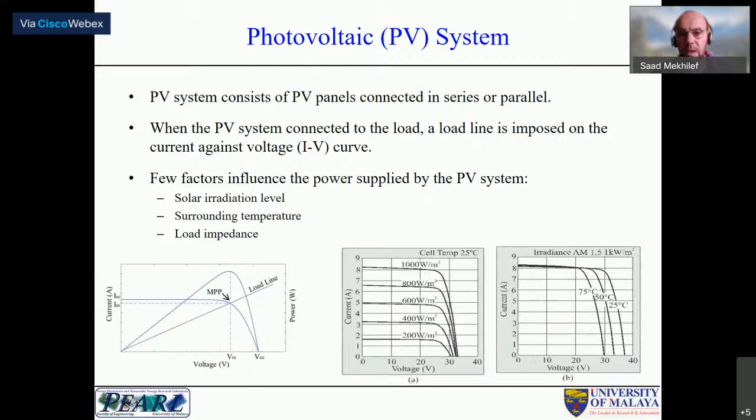This is just to review the characteristics. These are very common characteristics. We know that the PV output changes depending on the watts per square meter received. This is the current, and we call it the IV curve, at a fixed temperature, for example 25 degrees. The temperature also has an effect on the power produced by the cells. As the temperature increases, the open-circuit voltage drops, and there is a slight increase in the current. However, the overall power is reduced, and this is what we call the IV curve and the power curve.